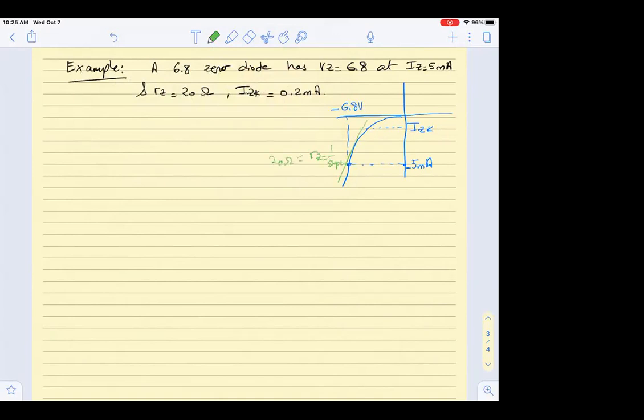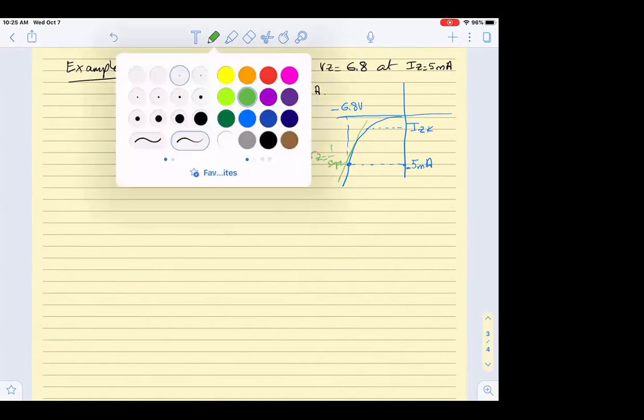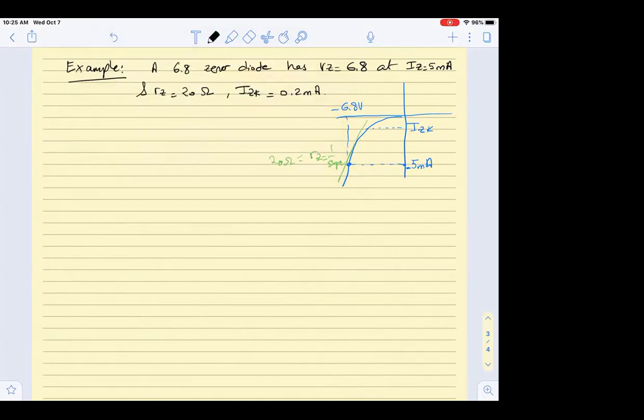Okay, so automatically I know that I can replace the diode by a voltage source and a resistor, but I have to see what is missing. Also, given that this diode is operating as a regulator across a certain node, I have here plus minus VO, and I'm going to plug in a load to regulate it.